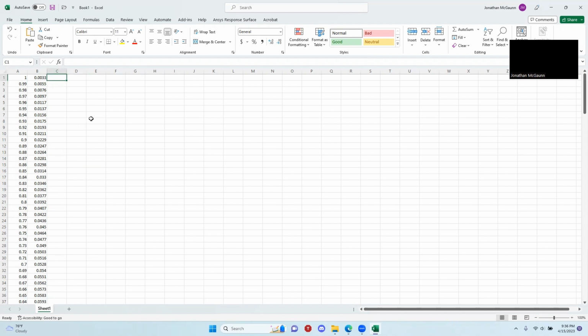So next, we are going to need to apply a scaling factor. SolidWorks, when you load in the coordinates, will read this in millimeters. I don't know why it does that. I guess it's just its default. Some other tutorials that you see on the internet will show them just uploading these coordinates in millimeters and then applying a scaling. I'm not too much of a fan of that.